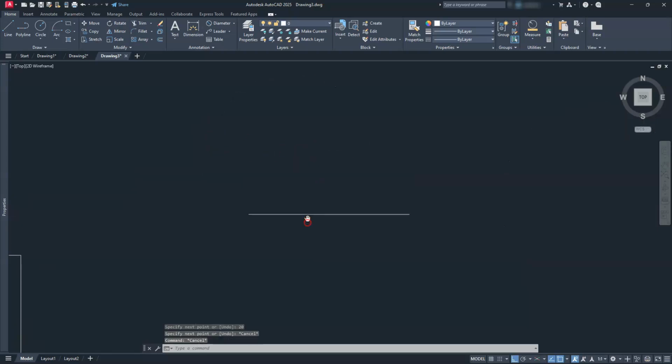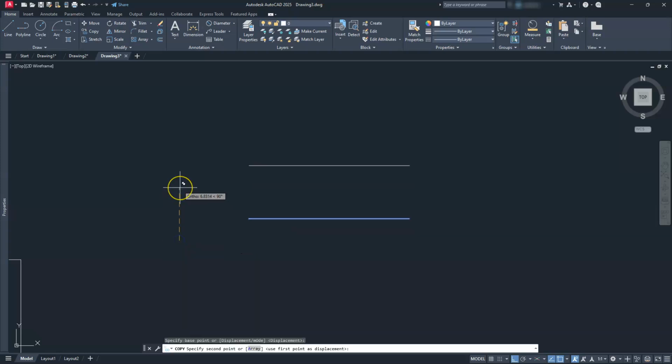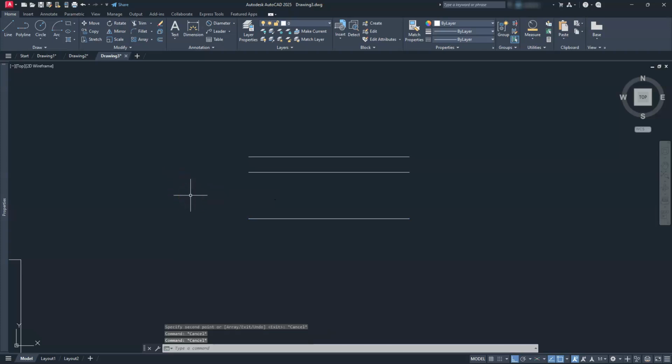Alright, remember when we were creating things with revolve, we have to think of it in portions of half of it. So we know that the outside circle is 16 as a diameter, and the inside one has a diameter of 12. So I'm just going to go ahead and select this line here, choose the copy command, pick a base point here, and then we can do some simple math in our head. Half of 16 should be 8, and then half of 12 should be 6. So I just typed in both of those numbers. One is 6 and one is 8. I'll go ahead and draw a line from that end point to this one, and the exact same thing on the other end.